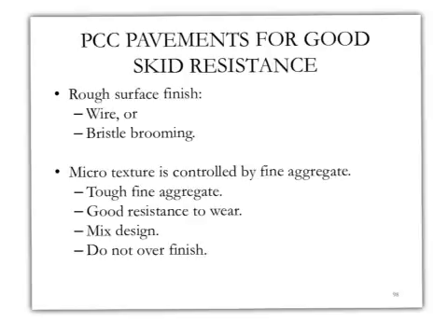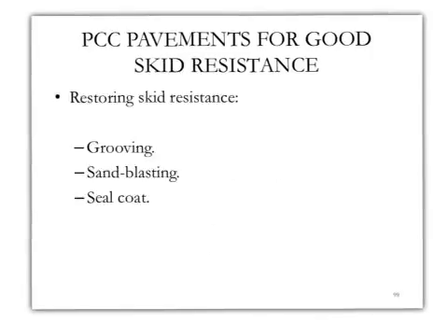Sometimes, especially when it comes to concrete pavements, we have very smooth surfaces. We think this is the best road because it's very smooth, but we should also think of having a balance between skid resistance and roughness. Keeping those two in mind will improve the microtexture of the PCC roads. Other techniques to restore skid resistance, especially for PCC, but also for hot mix asphalt, are grooving as well as sandblasting, all the way to seal coat.